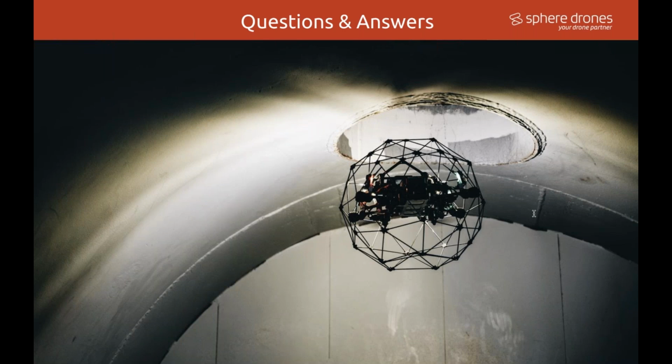Awesome. Thanks, Gregory. It might be great if you can just give us a very quick overview of general practice of what frames you would be taking out when going into your Pix4D, for example. Yeah. Usually I export with a frame rate of between 1 frame per second to 5 frames per second, something in that area. So if I'm just flying down a tunnel straight, you'd want more frames than when you're flying at right angles to a surface.